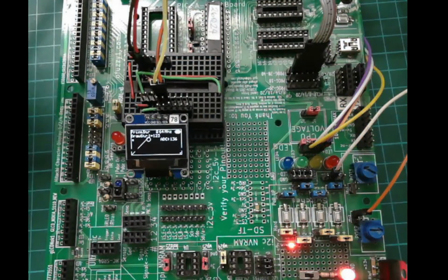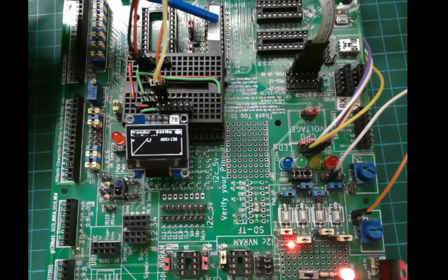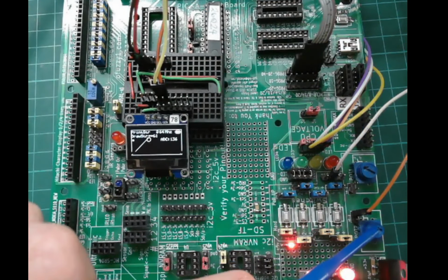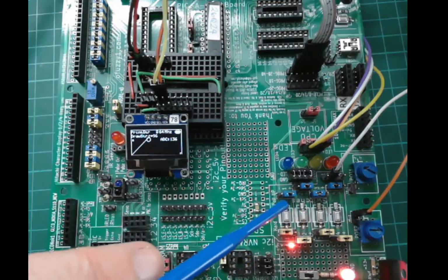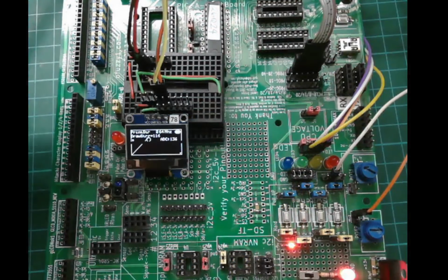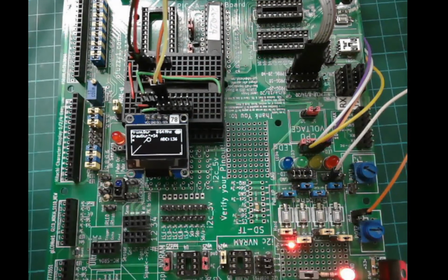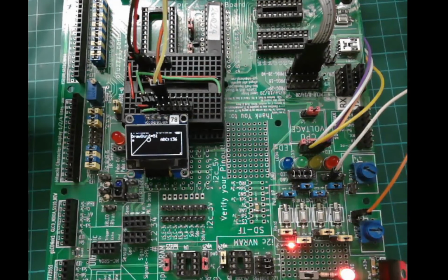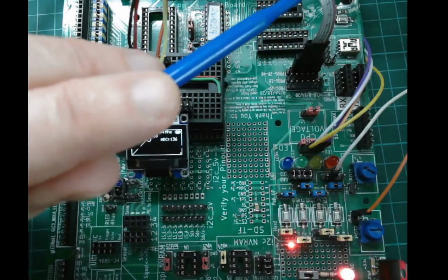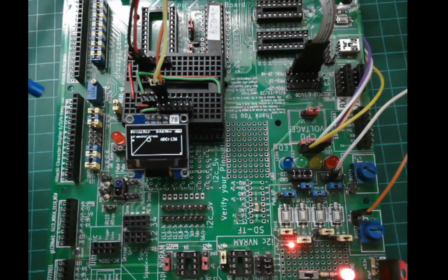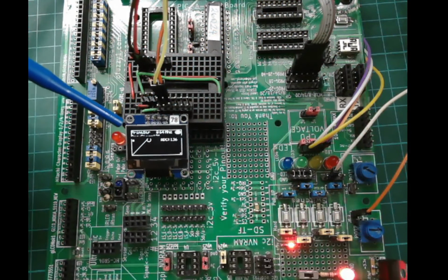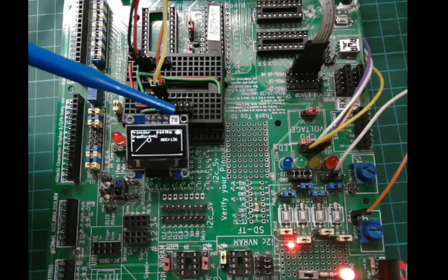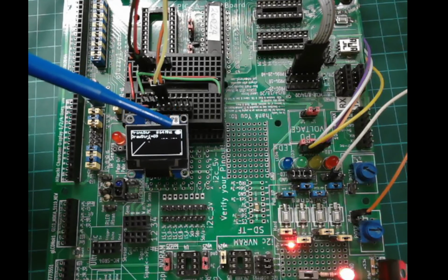So look, I've got the chip here, the Q24. I've got a potentiometer here. I've got a row of LEDs, some switches, and they're all connected via flying leads at the back of this thing. You can't see it, it's slightly out of picture, it doesn't really matter. The programmer is attached here. I'm using a PIC18xxQ24 today. We will use other programmers as we move forward. And as you can see, there's a GLCD sitting here operating on address 78. And what we're going to do is discover that.